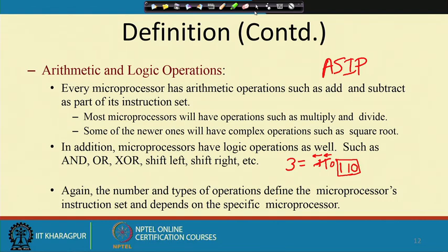Similarly, for shift right, this 6, if you shift right by 1 bit position, you get back 3. So that is division by 2. So we have shift left and shift right for doing these operations. That is one type of application of the shift operation. Another application is that many times we need to mask out certain bits from a pattern. To prepare this mask, the shift instruction will be utilized. We will see that later when we go into that type of application.